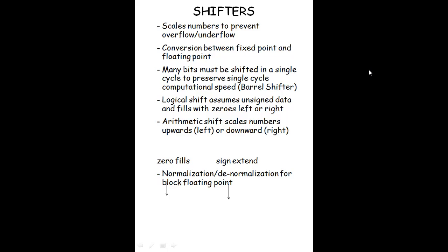The data buses, CB and DB, carry the operands that are read from data memory, whereas EB carries the data to be written to memory. The address buses carry the addresses needed for instruction execution.